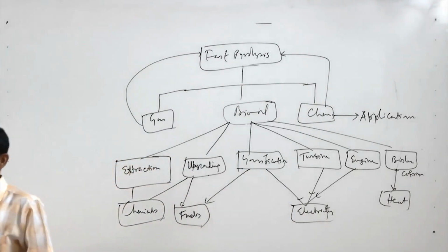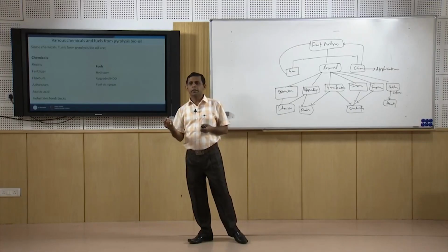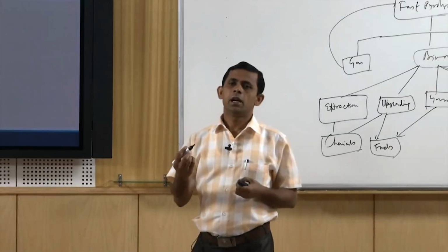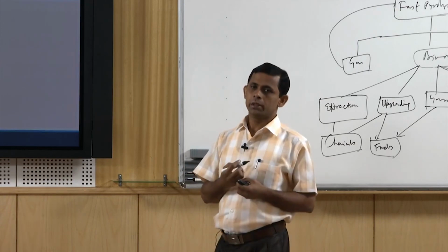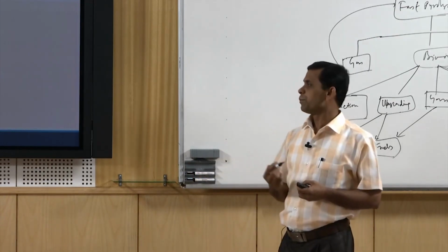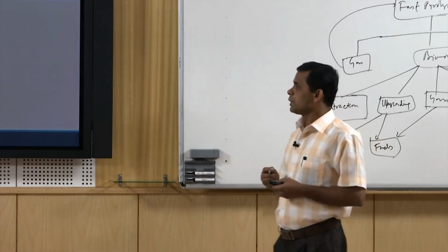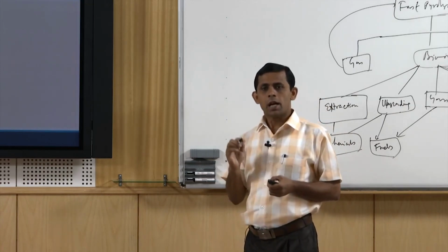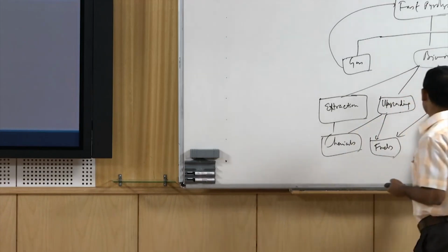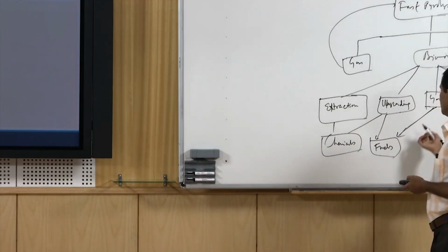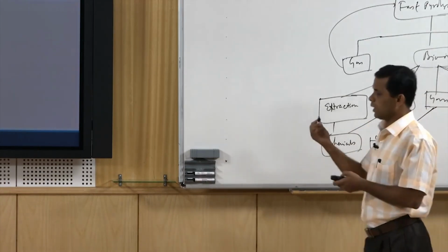The oxygen present in the bio oil is in higher amount, which is not desirable and reduces the quality of the fuel. That is why this deoxygenation is required, that is called upgradation. So, that fuel can be used, and once we are using gasification, we can get other fuels through FT synthesis also.